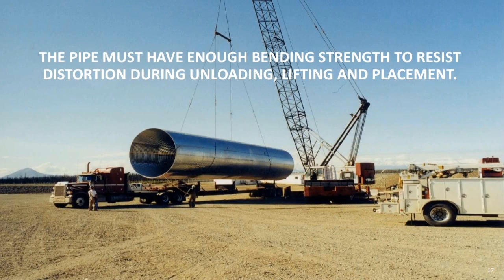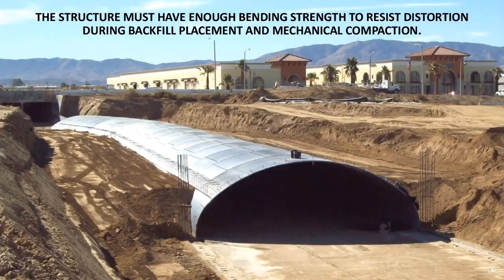Now, why is it important to have bending strength if the pipe is just going to sit in the ground and be covered by dirt? Well, you have to move this thing around, right? And it's this resistance to flexure that is crucial when handling a pipe in the yard or on the job site. It also comes in handy during the backfilling process, most sensitively on larger structures. The structure just simply must have enough strength to resist the distortion. You don't want this thing to rack at all.